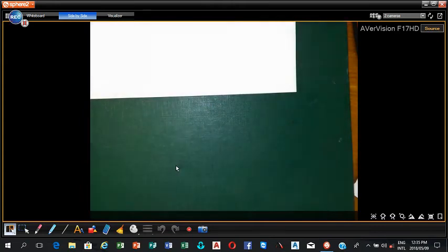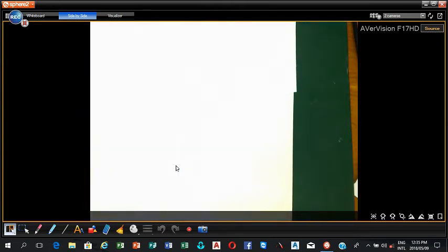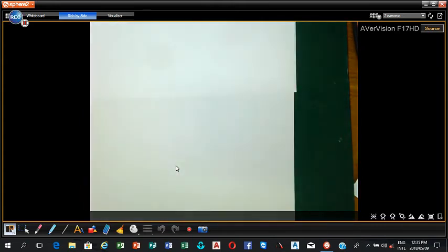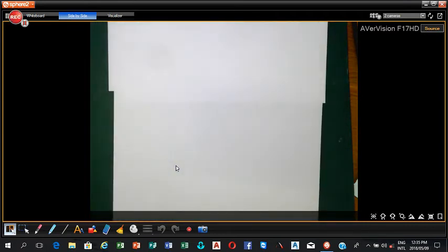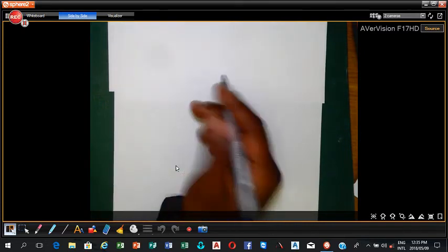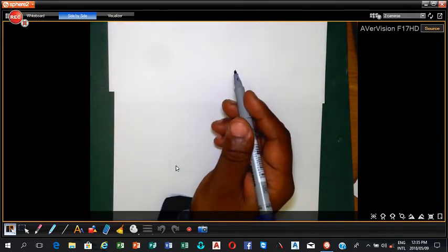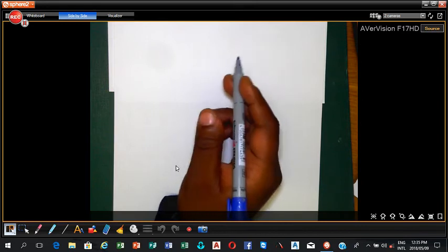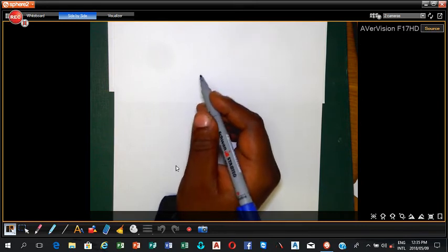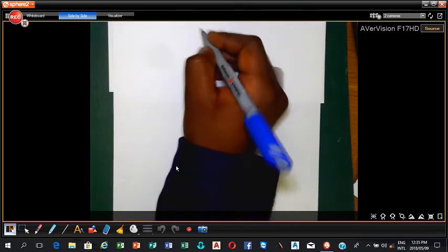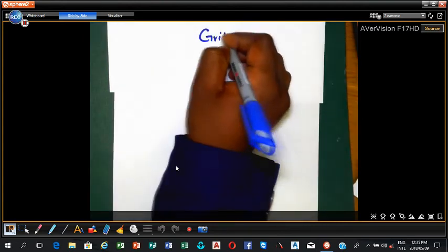Now we can see why it is important for us to have the screenings before we can move on to the primary treatment stage, by which we are dealing with sedimentation tanks at most. Right, coming to grit removals.